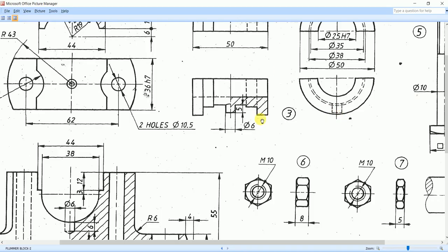But when we want to use the revolve option, we need to create the profile of the component about one side of its axis. This is the center of the bearing bottom, and this center corresponds to this particular line here in the side view. So this will be the axis. With respect to this axis in the side view, I need to create the profile. The profile is given by the hatched mark. This hatching represents the profile of the bearing bottom.